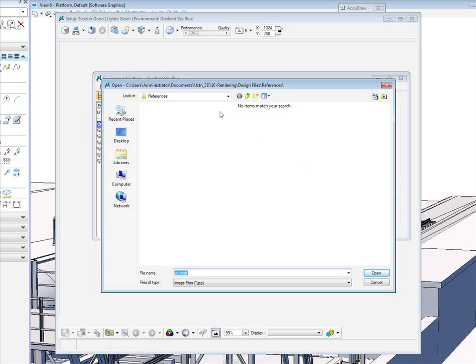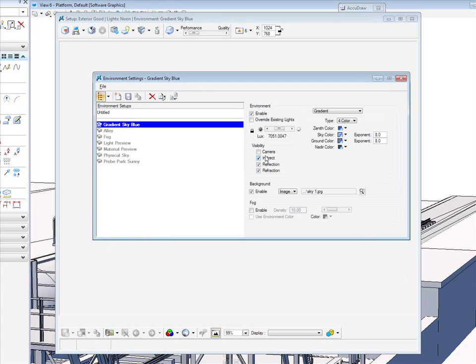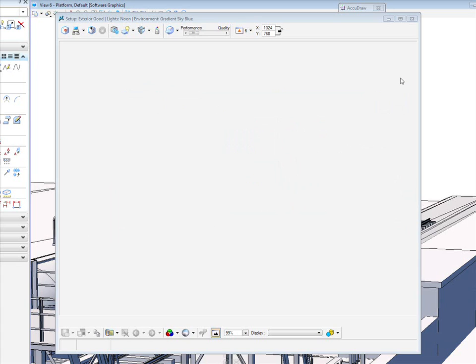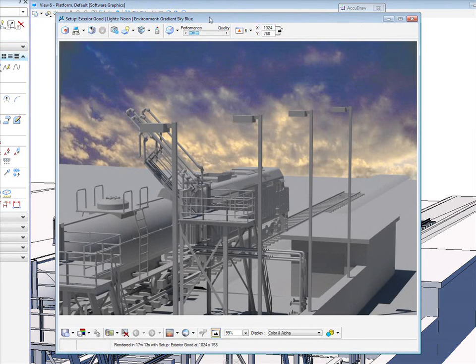dialog box opens up, and what we need to do is scroll back up to our folder for this particular session, and click on background images. There are two images, Sky 1 and Sky 2. I'm going to select Sky 1, and then I'm going to say save. Once I do that, I can close this down. I can then make sure that that one is the one chosen for this particular rendering, and I can now say begin. Wow, what a change.